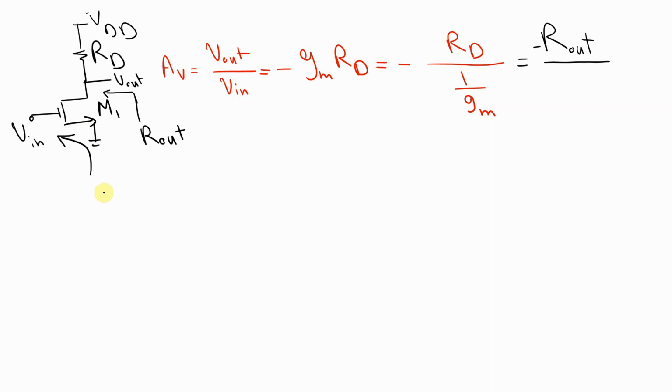When you want to calculate the resistance, you have to assume that the other voltage or current sources are eliminated, which means that when I calculate this resistance, let's call it Rx for the sake of simplicity. Okay, this is Rx here in the denominator. You have to assume that Vin is connected to the ground.